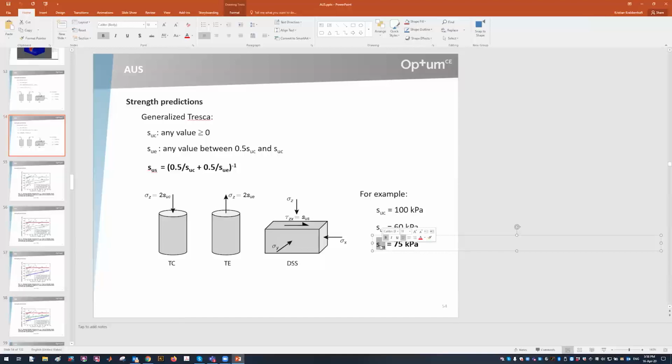So I would say anisotropy really comes into play when you have these very extreme extension to compression ratios, like we saw for those Norwegian clays, where it's down to 0.2, 0.3, something like that. Then anisotropy is necessary in order to really make sense of that data.